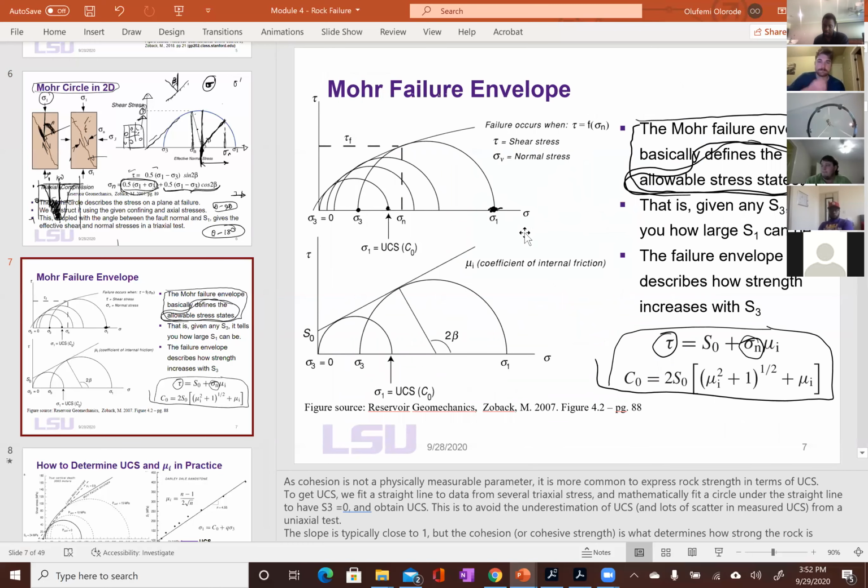Okay, I already came in here, and you get the idea. If you keep performing experiments at certain confining stress, the confining stress is always the smaller. There are 2 points to every diameter, right? The smaller point is always the confining stress. So you can draw the circle after performing the test. This is the confining stress or confining pressure. The other side of the circle is the maximum stress the rock can bear, which is the compressive rock strength.